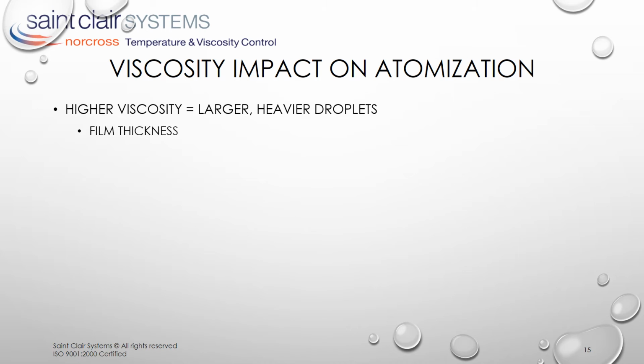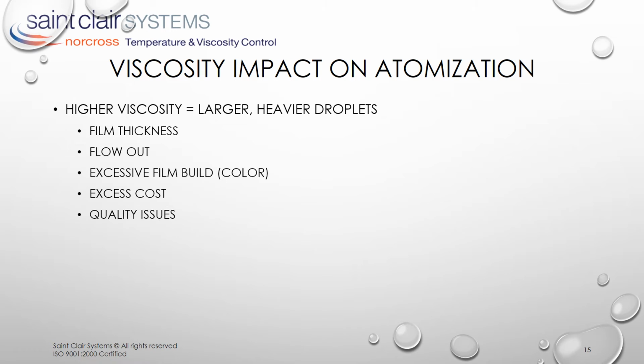Adequate film build is essential to good finish quality, but excessive film build can have a negative impact on the result. Too much paint on the surface not only increases paint usage, but can also result in runs, sags, and orange peel. At the extreme, this heavier film build can even result in solvent pop as the solvent trapped in the lower layers of the film migrates to the surface and escapes during the curing process. Or, in the case of 100% solids, uncured coating in the lower layers of the heavy film where the UV can't reach.